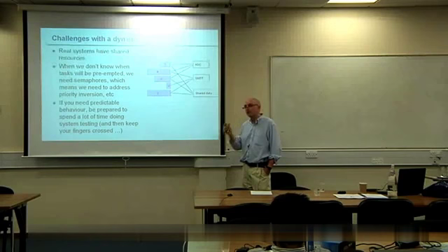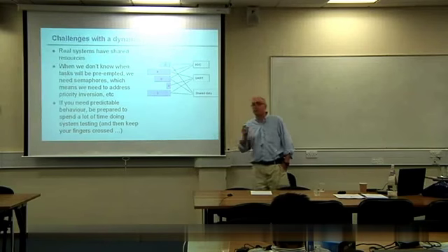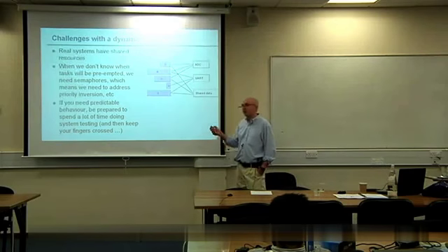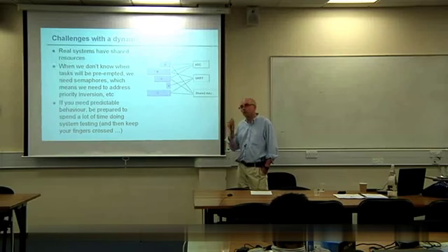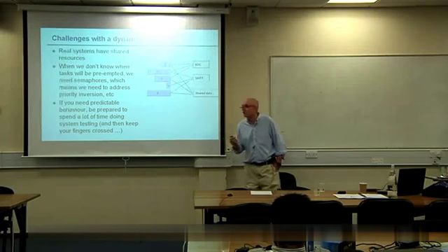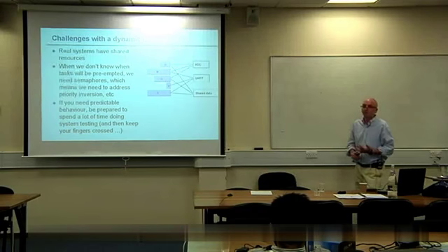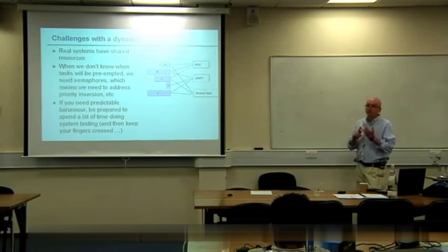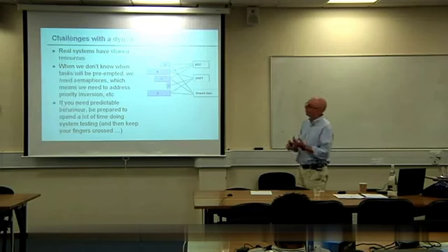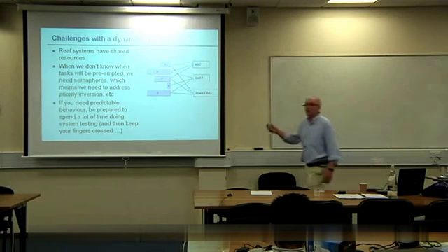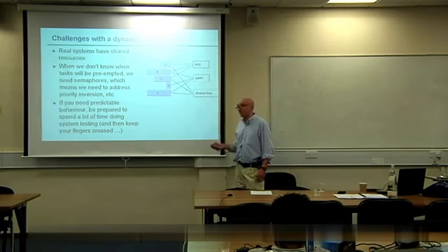That's a fundamental and profound difference between the systems. So in a time-triggered design, the conflicts don't happen. That is not priority inversion. That's correct task priorities. And it only happens because we know, even if we're allowing the tasks to interrupt one another, which we haven't done in the designs we've looked at up until now, you get much better predictability from a time-triggered system. And that's the reason why, because you don't have a task preemption issue.